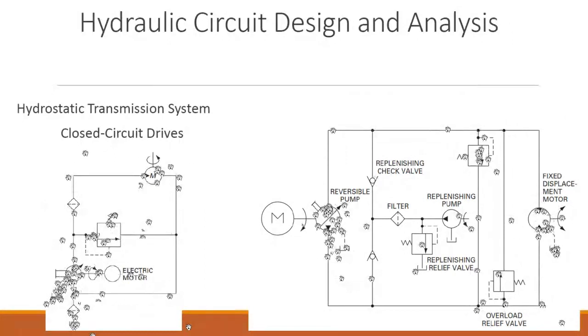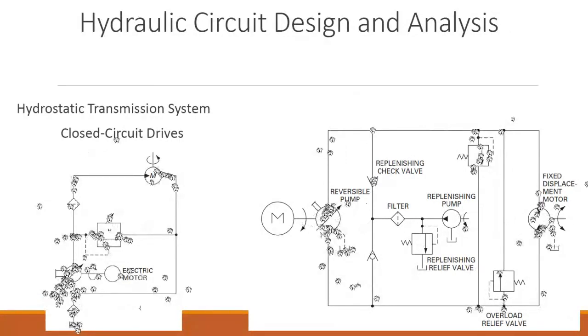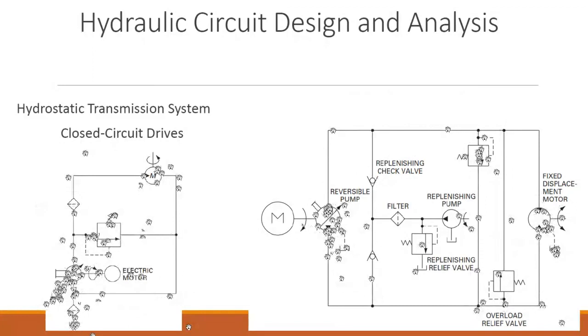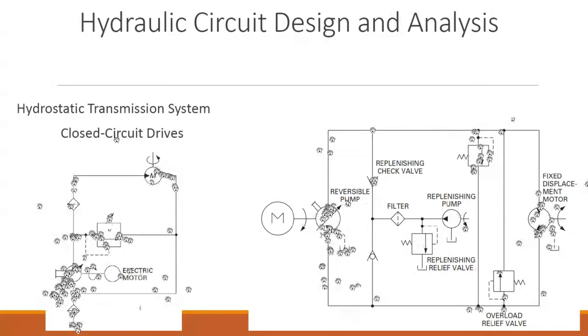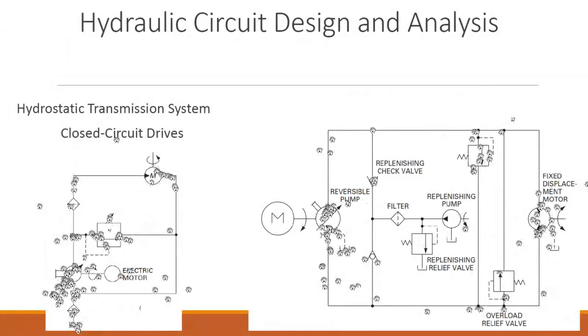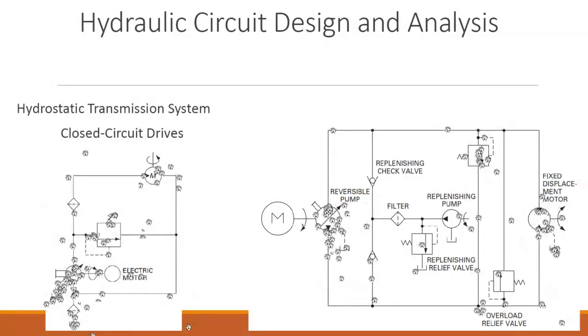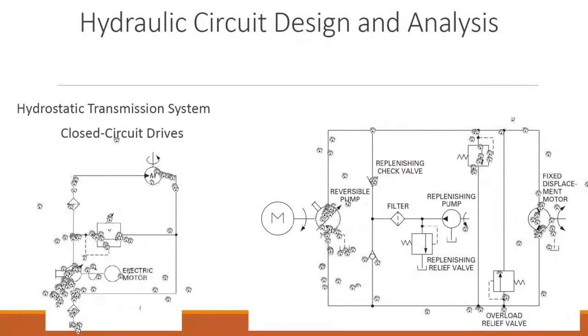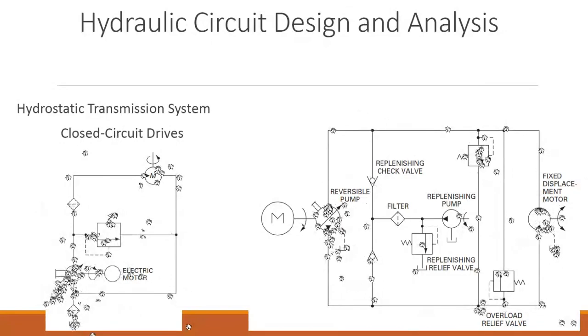If the pump is turned in the opposite direction, so that oil goes down instead of up, in that case the oil will come here. Okay, closed, no way, just stop. The remaining part of the oil would come here again, closed, then closed, comes here, moves the hydraulic motor in the opposite direction, then out into the line at lower pressure, comes here, closed, closed, closed, and then comes back here and continues circulating in this.